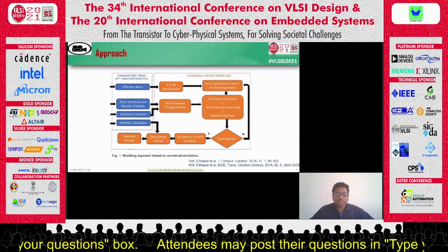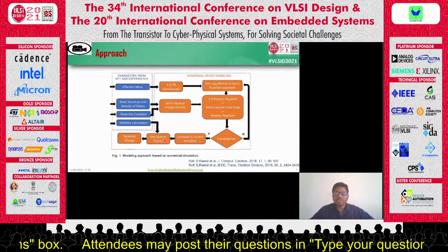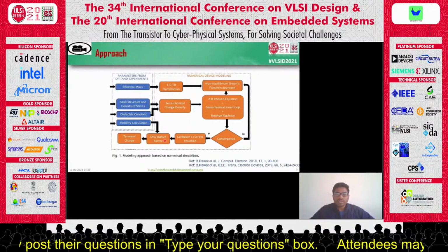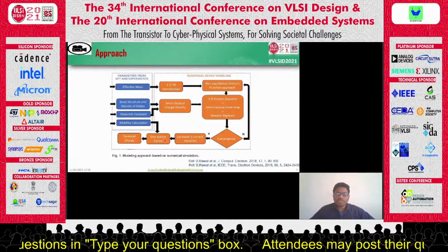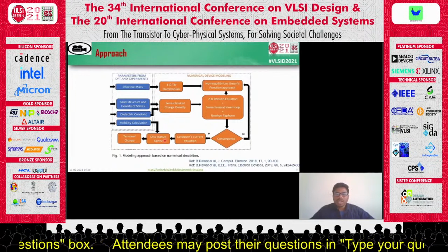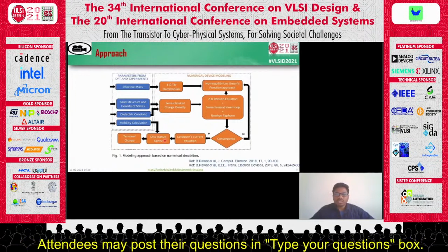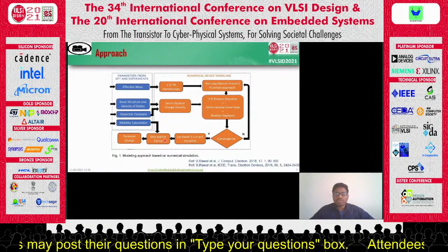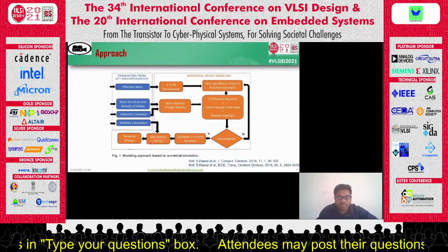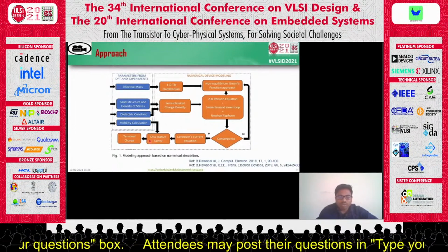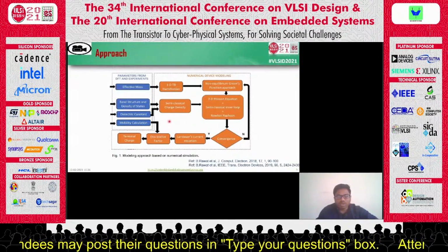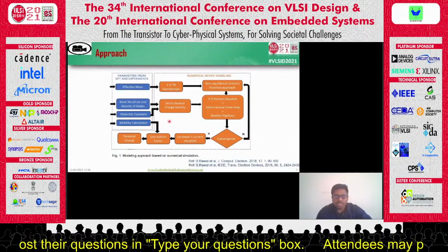We have validated our models with first-principles tools based on DFT simulations. However, our simulation models match experiments only qualitatively, due to the big difference between the considered device geometry and the limitations, such as channel length, interface states, and contact resistances, of the currently fabricated 2D material-based field-effect transistors. And for the Si FET, we have used the NanoMOS model based on the same approach, and we have taken the transport along the low effective mass directions.